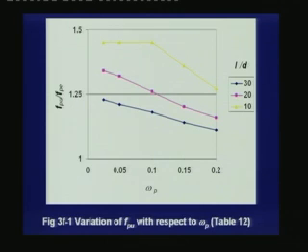As we had seen for bonded tendons, the code allows us to use some approximate values for the depth of the neutral axis at ultimate, xu, and for the steel stress at ultimate, Fpu. For a bonded tendon, the tables were given in terms of reinforcement index, where Fpu was normalized with respect to 0.87 Fpk, the maximum allowed stress in the bonded tendons. For an unbonded tendon, the steel stress is normalized with respect to the effective prestress, and the table is again given with respect to the reinforcement index, which is the ratio of Ap times Fpk divided by b d fck.